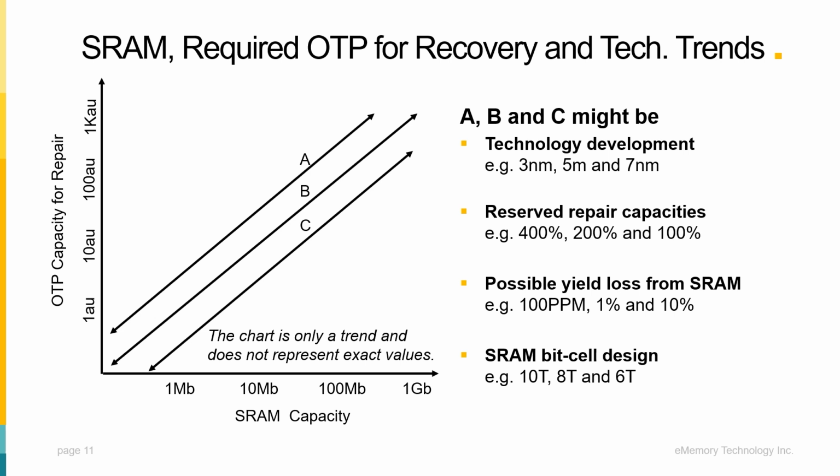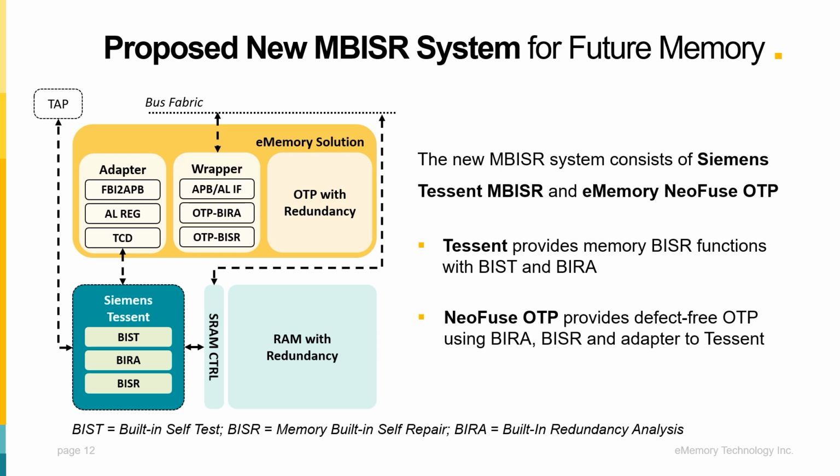Therefore, we have developed a new memory built-in self-repair system. As illustrated in the diagram on the left, this architecture integrates eMemory's OTP with the Siemens Tessent tool for a comprehensive DFT subsystem. Tessent includes designs such as built-in self-test, built-in redundancy analysis, and built-in self-repair to achieve the memory repair function.